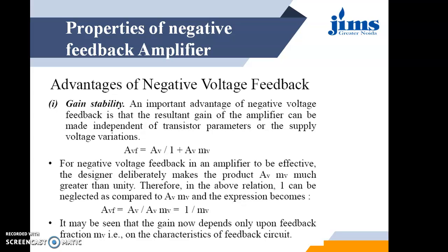So the very first advantage is gain stability. What is gain? Gain is the amplification factor of the input signal. Whatever voltage we apply at the input, we are looking for the magnified value of that input at the output. That is called the gain. Stability of gain means that whatever the magnitude of gain, it should remain the same throughout, whether the input voltage is changed, input conditions are changed, temperature is changed, environment is changed, or timing is changed. In all conditions the gain should remain the same. This is called gain stability.